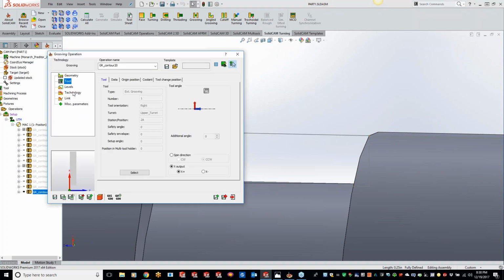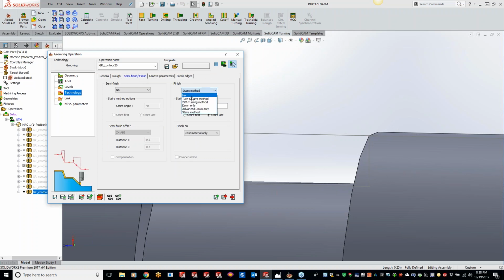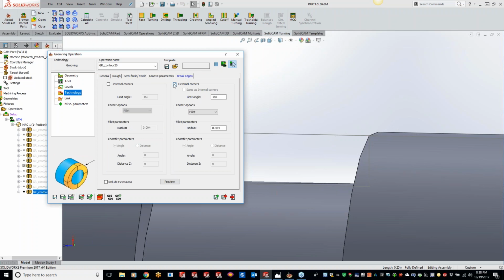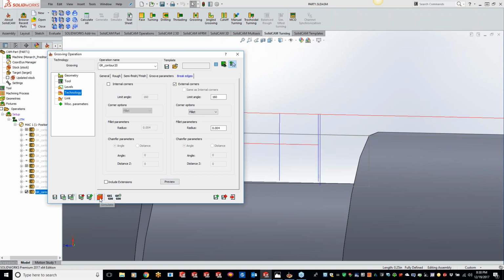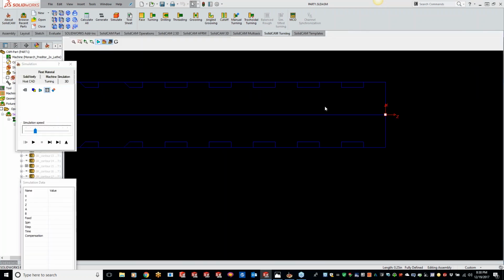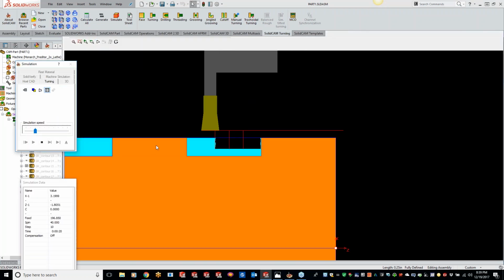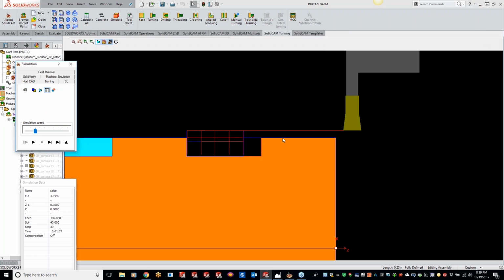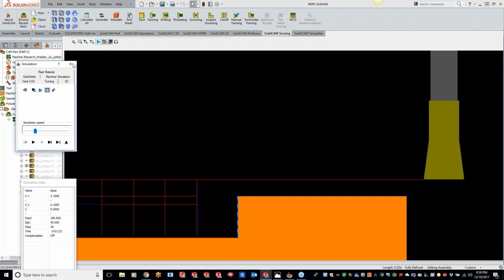So let's get our groove. Let's just do an ISO turn. Now if we go to edge break, do external corners, and we can tell it, do you want a fillet or a chamfer? We can put what size angle that we want in there, distance, or like I said, we can do a fillet, and what size radius do we want in there. So just do save and calculate here. And did it not pull up my...